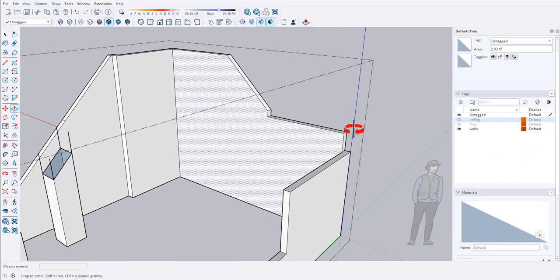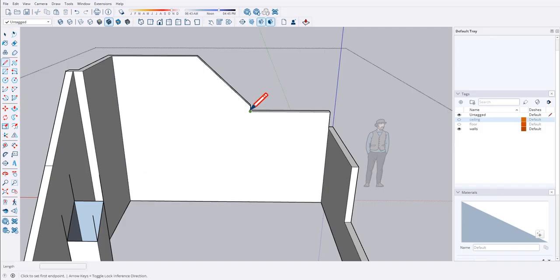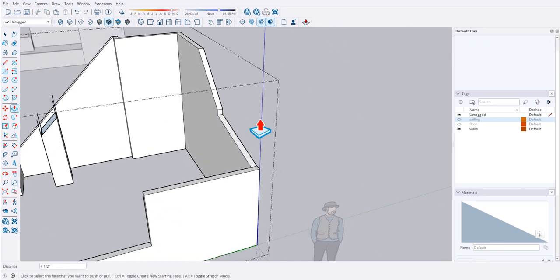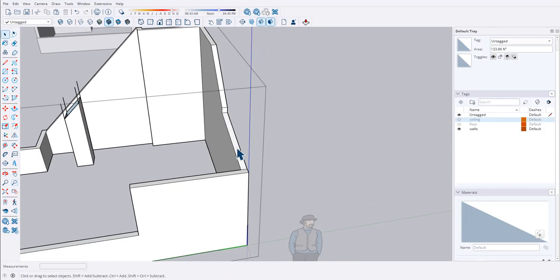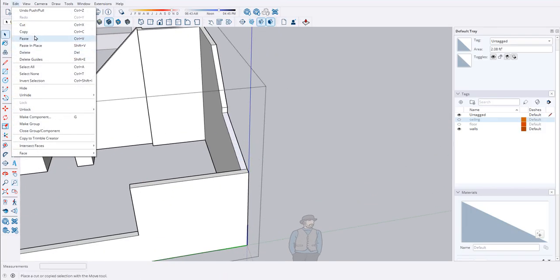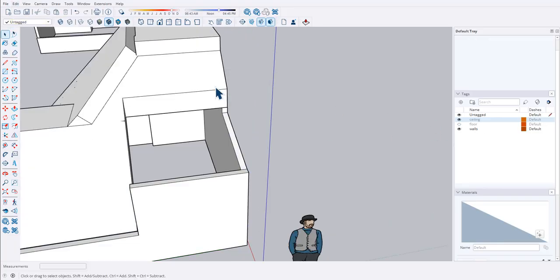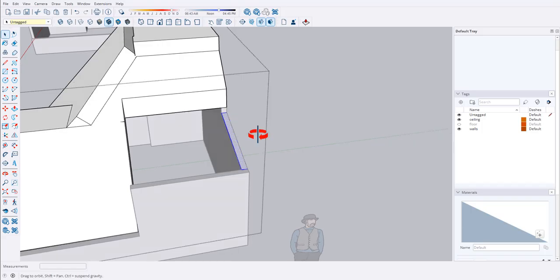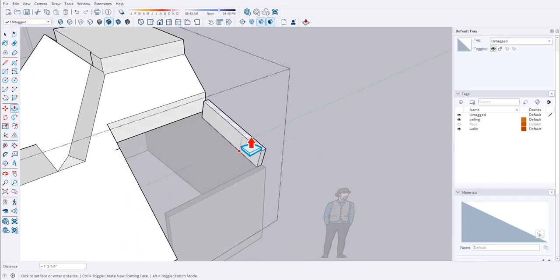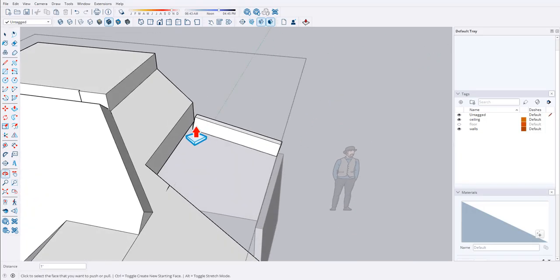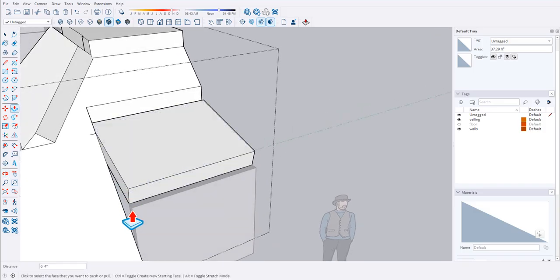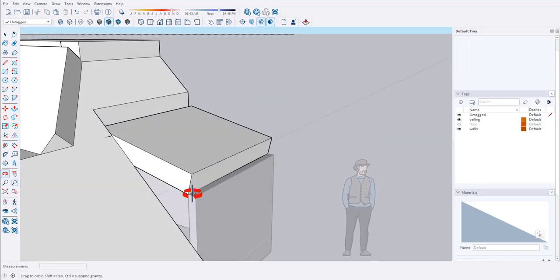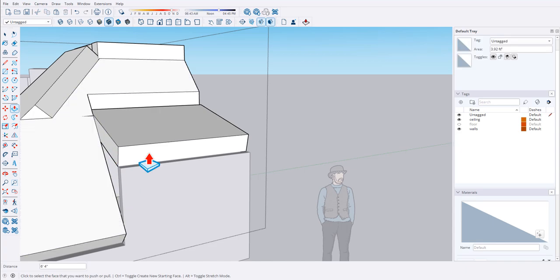Okay, so we're going to say that there's some sort of plane from here to here. That comes in at this angle because you're telling me there's a certain wall height here you measured. I'm going to select this surface, edit, copy, make the ceiling again, double click in here, edit, paste in place. P for push pull, I'm going to move this up 12, just like the other walls we did. Click here and I'm going to go across to this point, click. And there's actually going to be a little piece of wall here.